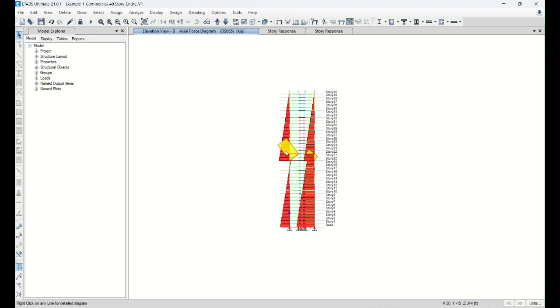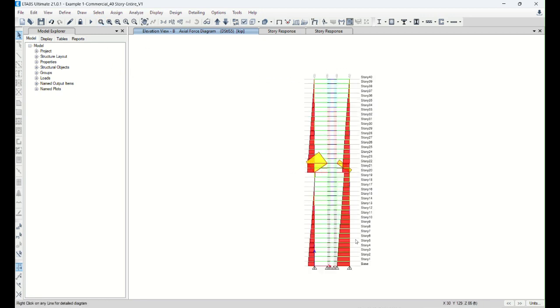So I think one thing is that we design due to the gravity load. We design the column based upon gravity load. Now, including the wind effect, we combine the effects, we really design one more time, make sure every column is working, but most likely those columns tied through the outrigger are not gonna work, so then typically we need to size up, increase the size based upon our wind effect.